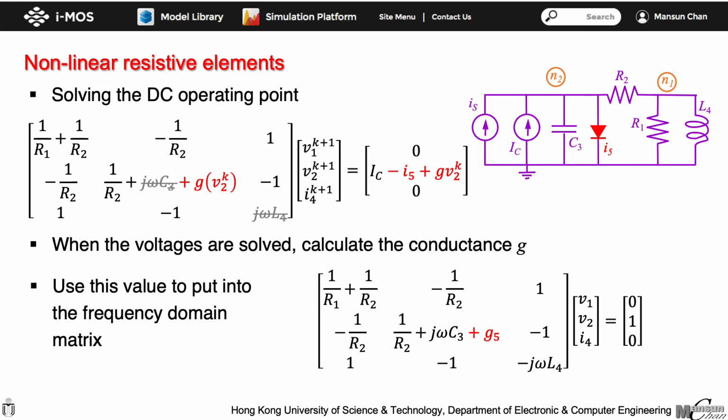We can then solve the AC matrix by removing the DC sources, add back the one for the input signal source, and allowing omega to vary as the independent variable. Using this matrix, we can obtain plots for the amplitude and phase of the state variables as a function of frequency. By including the inductor current as a state variable, its frequency response is also solved explicitly.